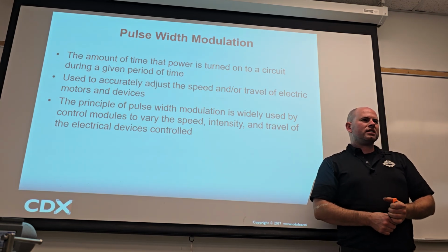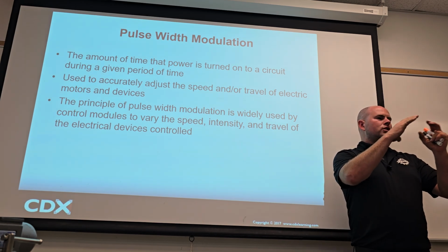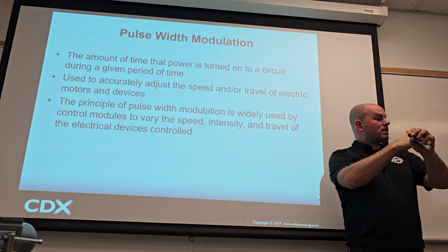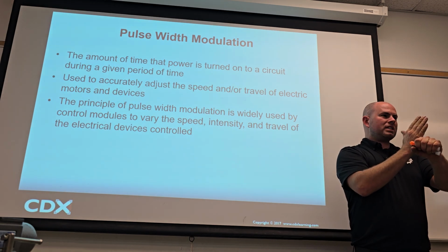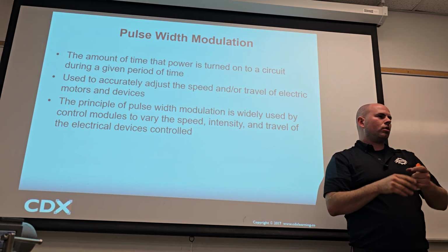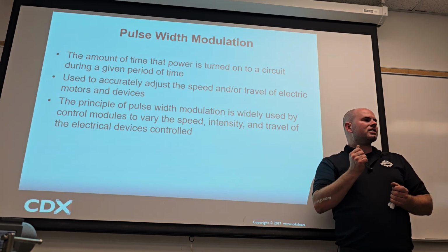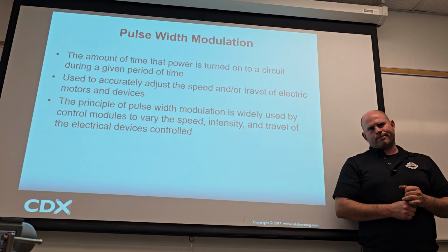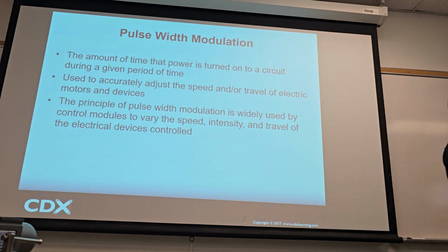I was talking with a friend, and he said, why don't you oscilloscope that and just see? Because sometimes when you get a dead section of the motor, it'll get really slow. If it's already running, it'll skip past the dead part and keep working. But if it happens to stop on the dead part, when you go to start it, it'll pull high current and blow the fuse. It made a lot of sense. And when I did the check, it was like, oh, there it is. There's no doubt. OEM fuel pumps are $800. You could be gutsy and just get a new fuel pump, but then when you spend $800 and it doesn't fix it, it kind of sucks. Right?